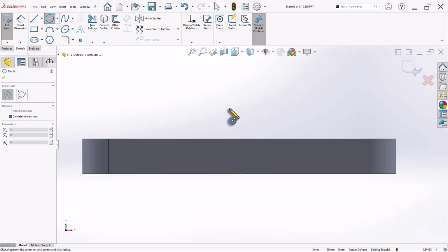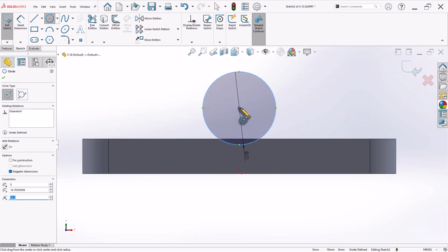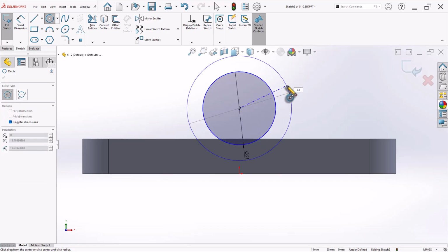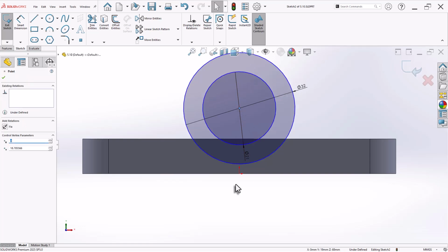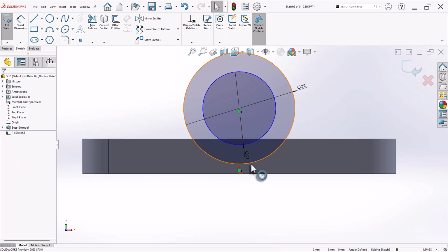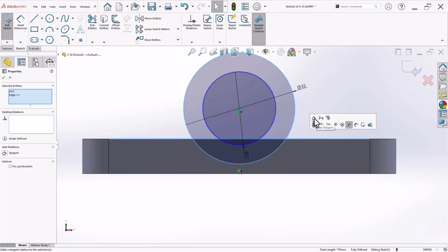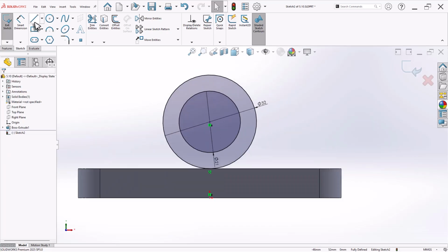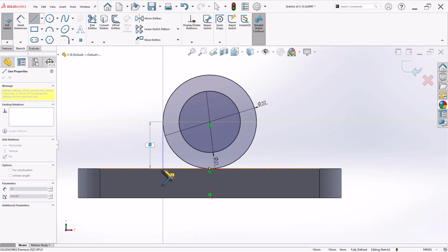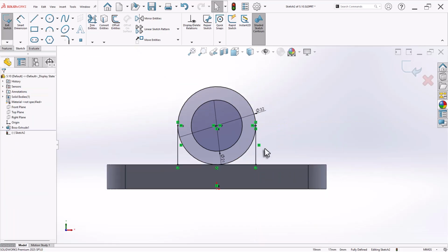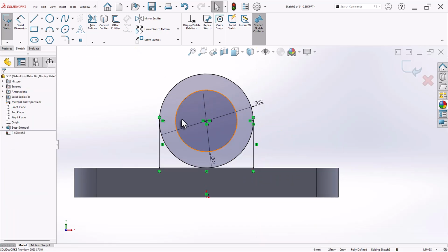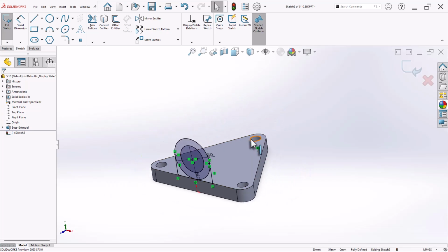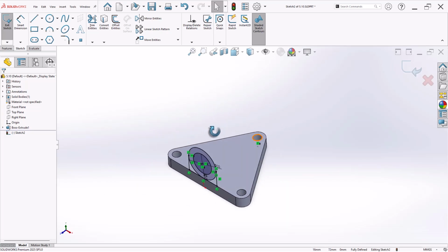Now let's use shortcut key and draw the circle having diameter 21. And this is of 32. So let's make them first vertically aligned. Let's make this circle and this tangent, and let's draw a line from here over here and this one. So let's create a region.